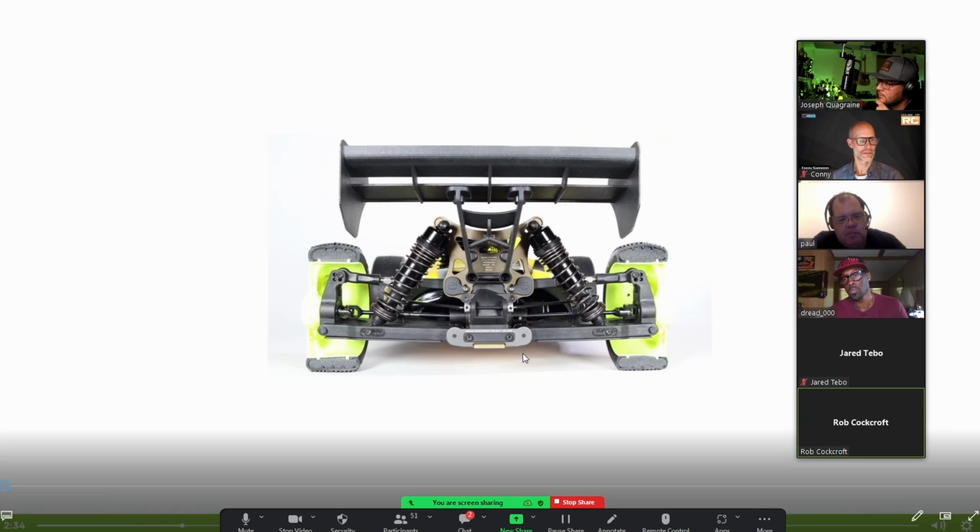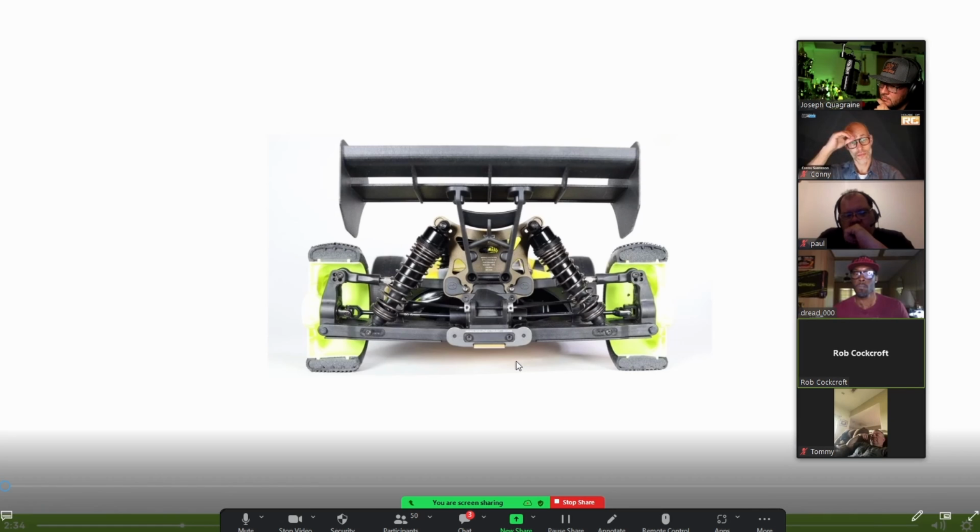In theory, is it possible to have a situation where, just purely from a geometrical point of view, you can actually have exactly the same roll center height by moving both the upper and the lower arms, so you end up with that intersection point just further outboard or further inboard? Yeah, you can have exactly the same roll center height. What would the effect be of having that? Would that just be the change in support that you gain, but have the same in on track feel?